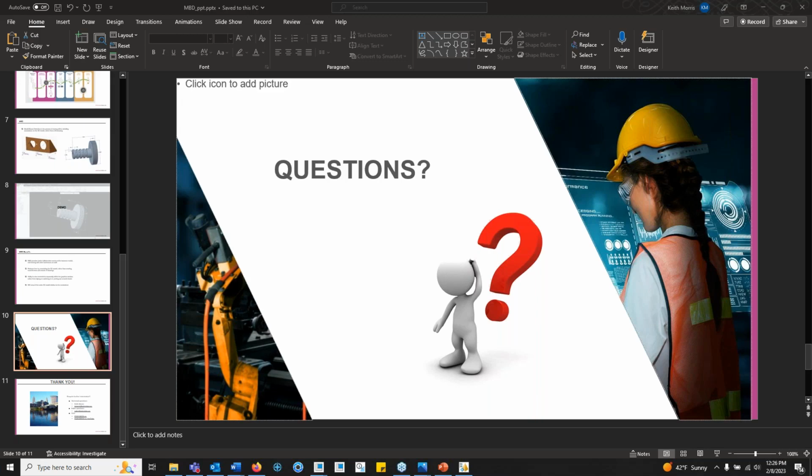Claudia, you had another question. Is there any way in the default view to not see all the dimensions put together? In combined view it is not published, but still appears in Creo View. Yes, that's why that model view is created. It resembles the default view where there's no dimensioning at all. It's just the model. If you have that as a combination state, that's why I turn the default one off and make one that's just the model instead. It'll show up in Creo View.